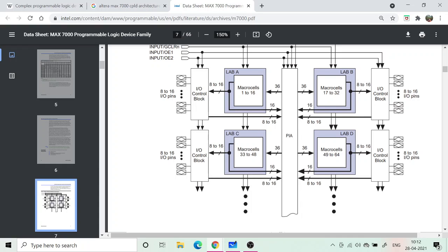Routing means making more complicated connections which cannot be contained in one macro cell or even in this 16 macro cell; you need to make them the input of other macro cells, and thereby achieve a more complicated function.